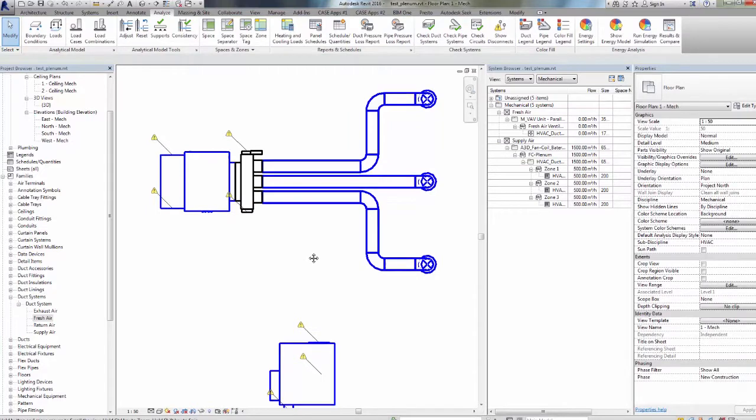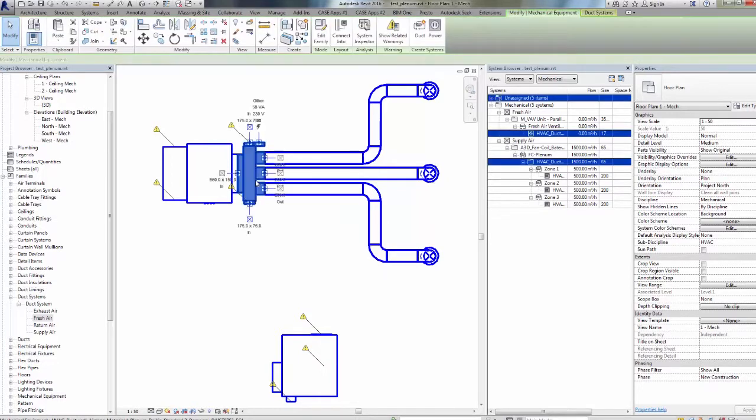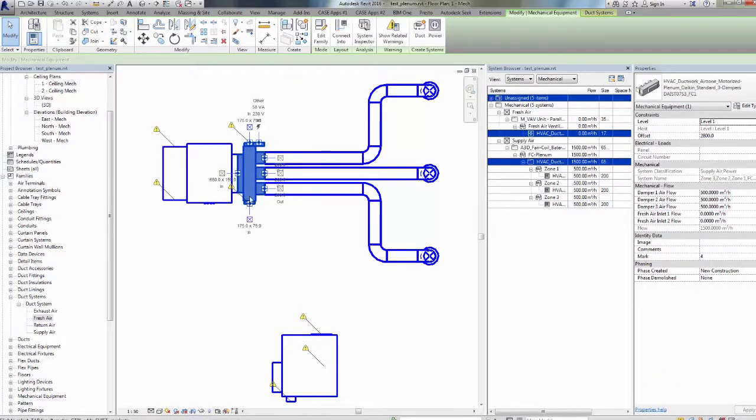We are now adding the fresh air. This means that each outlet airflow will be the addition of the airflow coming from the indoor unit and the airflow coming from the fresh air unit. Then, the fresh air unit airflow must be deducted from the indoor unit global airflow.